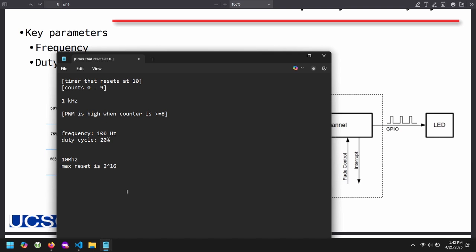So create a frequency of 100 kilohertz, duty cycle of 60%. Okay. This will be the last quick math question at the moment, and then we'll move on to some code. Okay, go and do this. Actually, I'm going to change it. I'm going to say, maybe not. Let's say 50 kilohertz. Okay, what should our timer's reset value be?